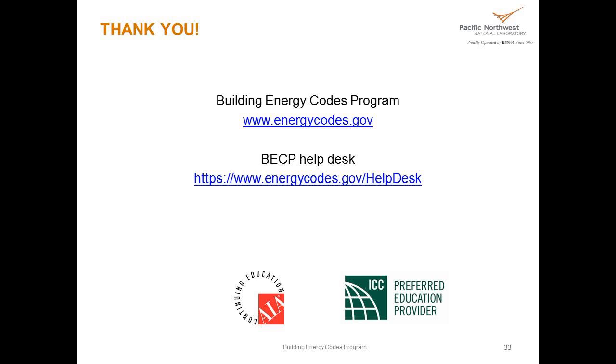Especially in 90.1, I know that the committee has looked at what is available today and what is likely to be available in the future, and there are some conservative updates to the lighting power densities. So the lighting power densities are moving downwards to follow the penetration of LEDs in the market.